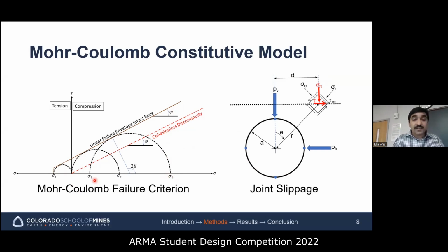The Mohr-Coulomb failure criterion is also considered to be a reasonable approximation for discontinuity, typically using cohesion as 0, whereas friction angle controls the strength envelope. To assess the failure along the discontinuity, the joint failure criterion is used with substitution of stress components that are normal and shear along and near the discontinuity.